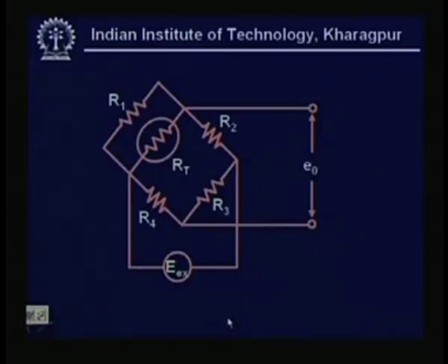It won't be fully linear, it is not possible because it is already a nonlinear device. It is an exponential fall, but if you use a resistance in parallel for a small range, it will become linear. So, by sacrificing the sensitivity, I am making the thermistor circuit linear. This is my circuit as we discussed.